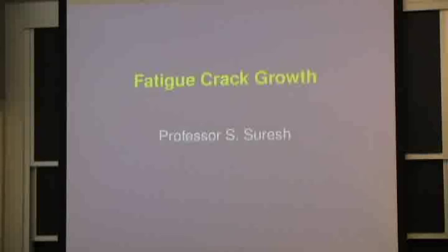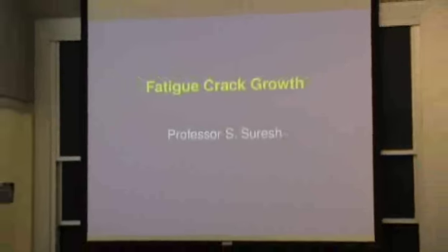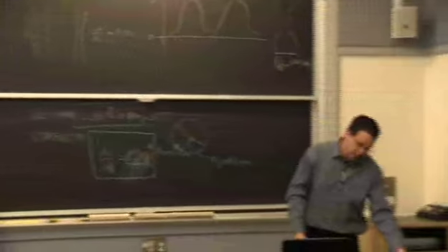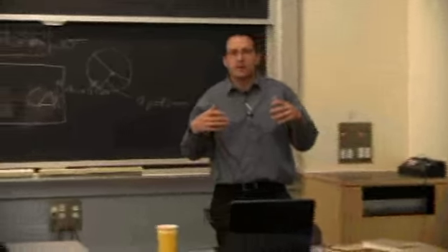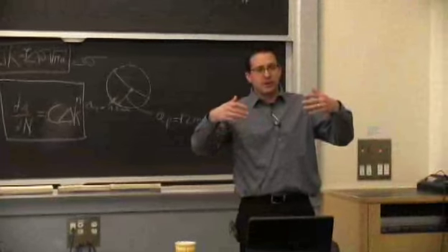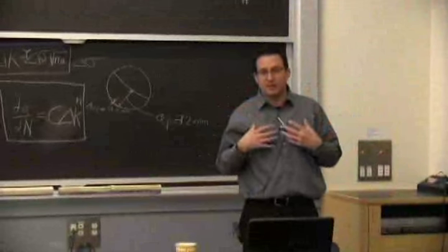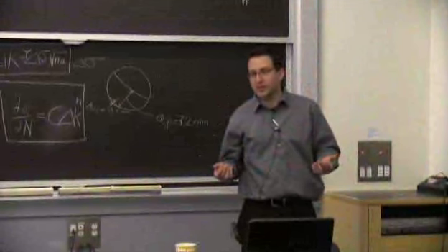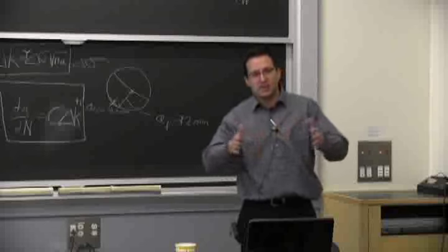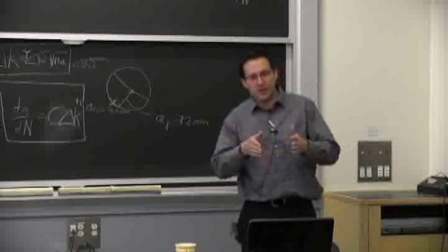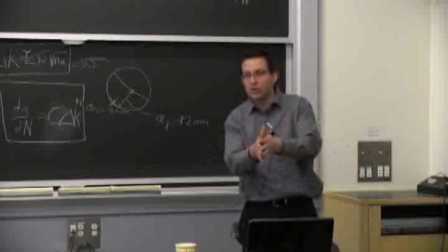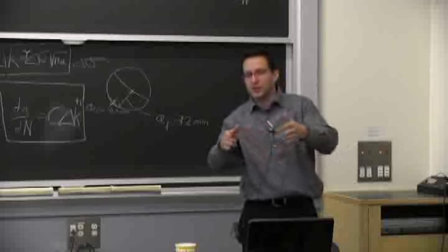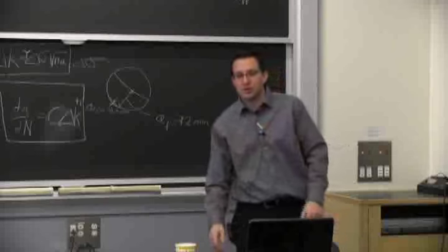Now, it's not all metals that will do that, and it's not in all conditions, but it gives you an idea that it's really progressive. And the reason we see those lines is the plasticity at the crack tip. When you try to inch back and forth and somehow you manage to extend your crack, you will form these little ridges, essentially.